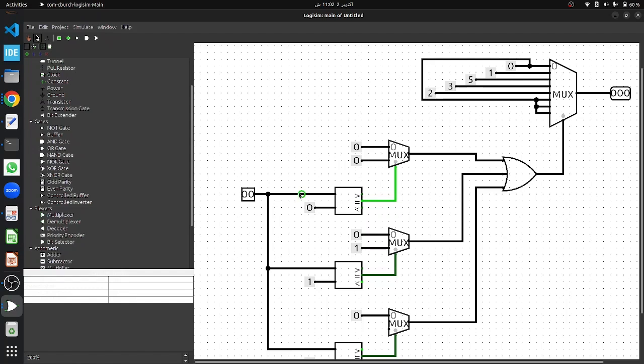So first we just walk through it. You can say if the opcode is 0 0 and it gets compared with our 0 value, so we are going to get an output of 0 from this mux, which is going to get ORed with all of these signals, and this OR gate will generate an output of 0, which is going to select the 0 input of this mux, so we will be getting a control signal of all 0, which is going to perform an add operation, right?